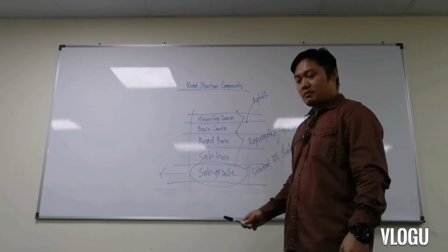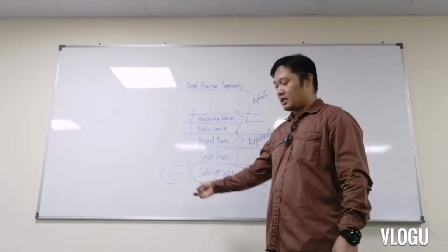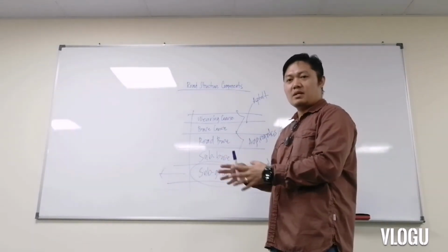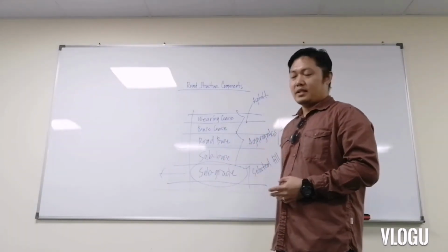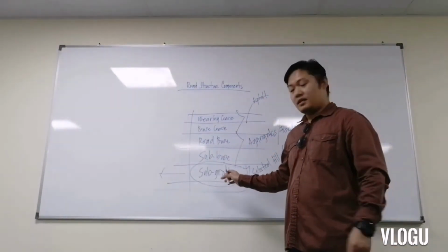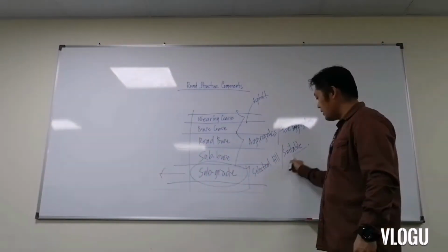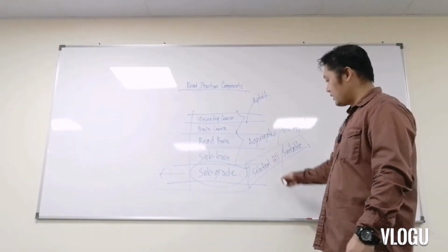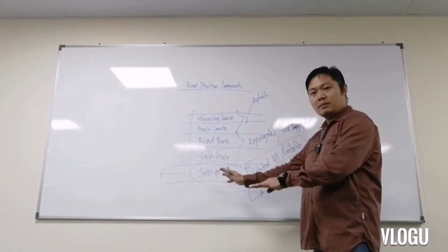And let's say, for example, if you found out that the plasticity index and the moisture content will be out of the tolerance based on project specification, it will be considered as unsuitable material. So we are going to scrape, or remove, the existing roadway subgrade, and at the same time it will be replaced by selected fill.